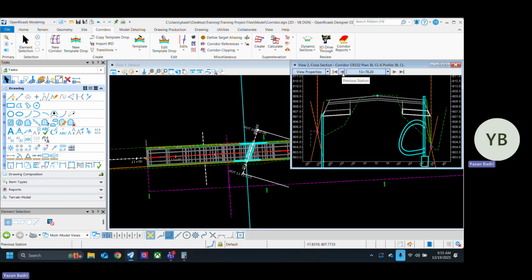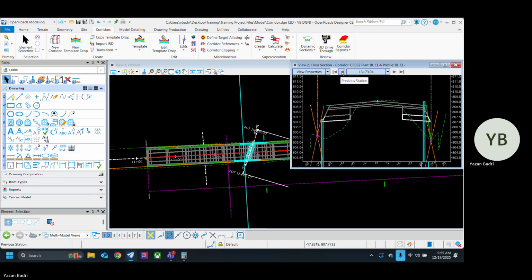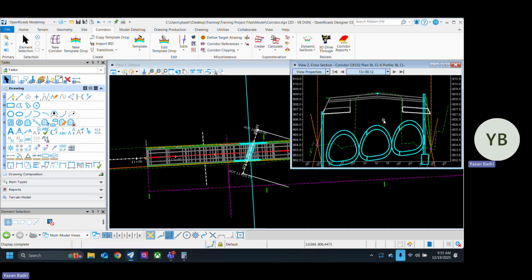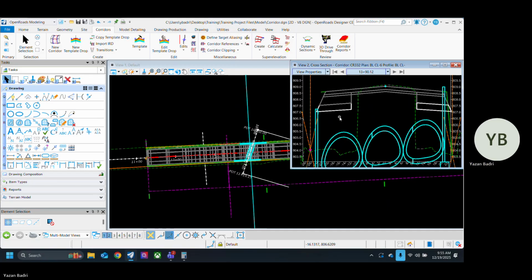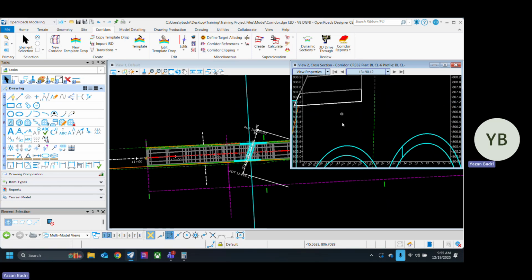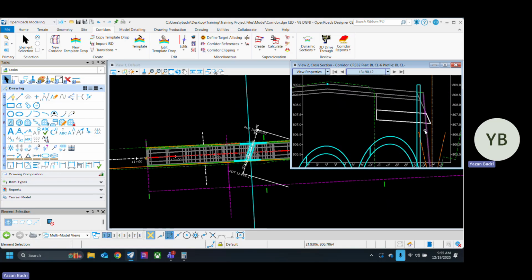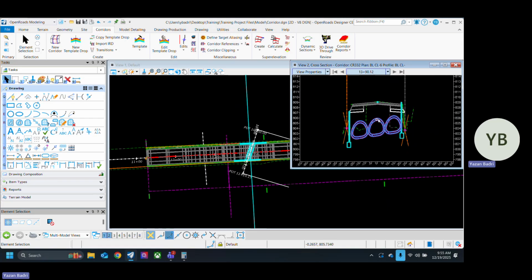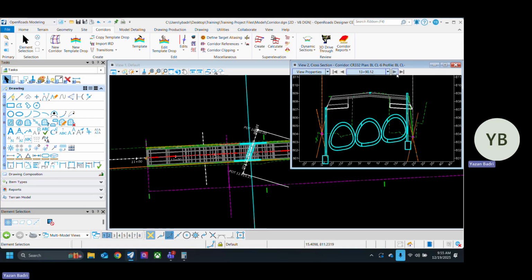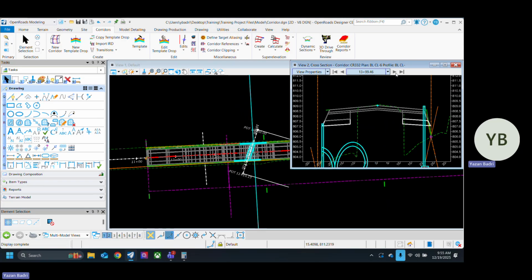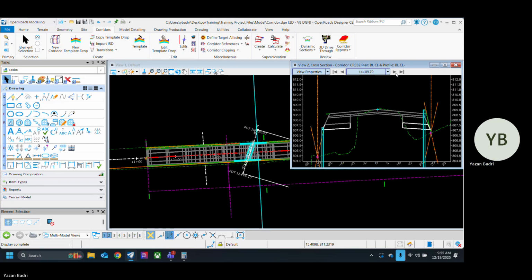Cover, where you mean on top of the culvert? Yeah, plenty. It's not 2 feet right now. But on this side it's different. Oh, we'll come back to it and adjust it. Okay, so it's looking good, right? Or over 1 foot of cover, because I think 1 foot was like the minimum. Yeah.